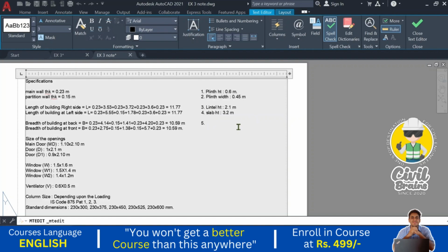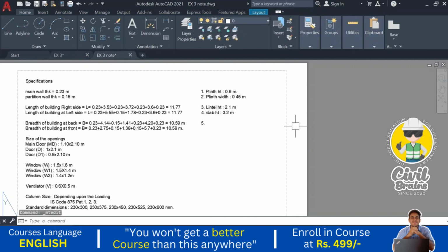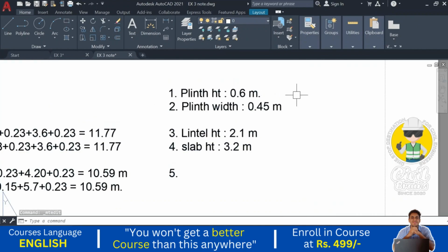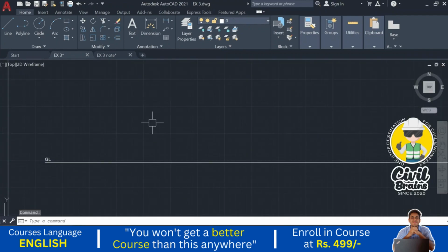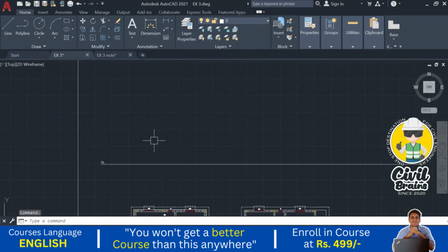Next, parapet. So not parapet, the first floor will come. So here the parapet will not come, the first floor will come. So those dimensions we will add later. So these are the things: plinth height 0.6 meter, plinth width 0.45 meter, lintel height 2.1 meters, slab height 3.2 meters. Okay, I just go to the drawing, I just draw the levels first.